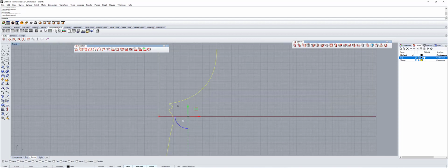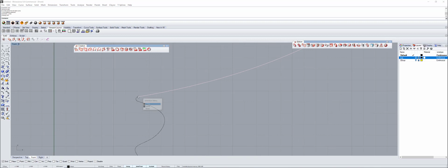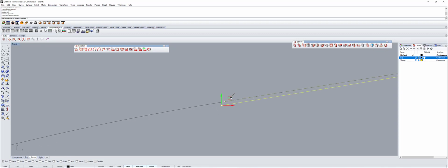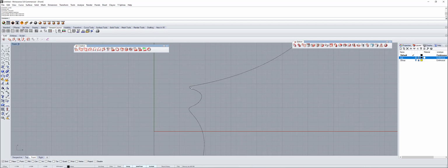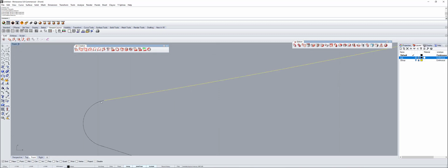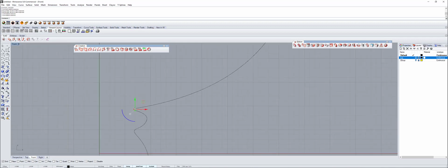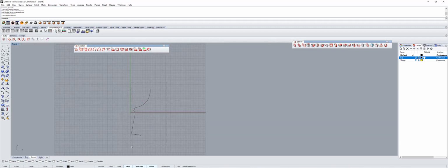I'm going to undo this. I'm going to show you when those errors happen. For example, the tangent that we did over here didn't touch one of the two lines, this one or this one. So I'm going to do the sample with this one. I'm going to enable F10 to see my control points. And for example, it looks like I finished good, but no, it didn't finish correctly. So this line is not ending at the end of this curve. So I'm gonna do the command join.